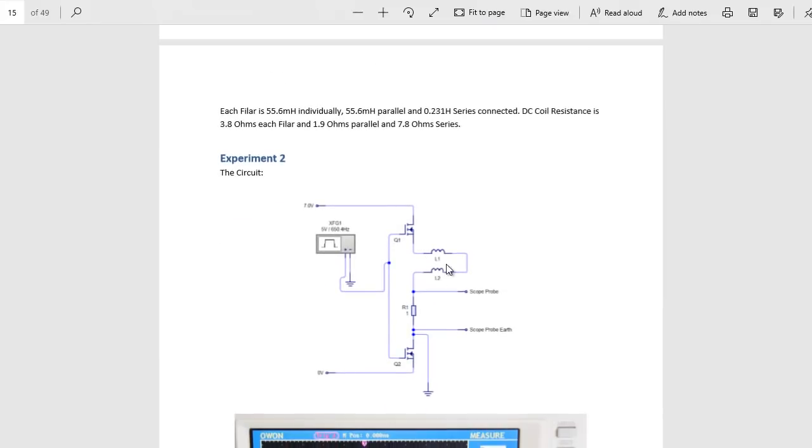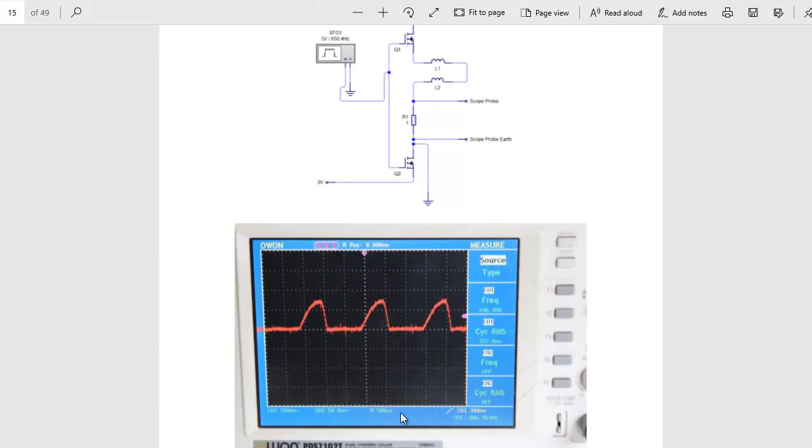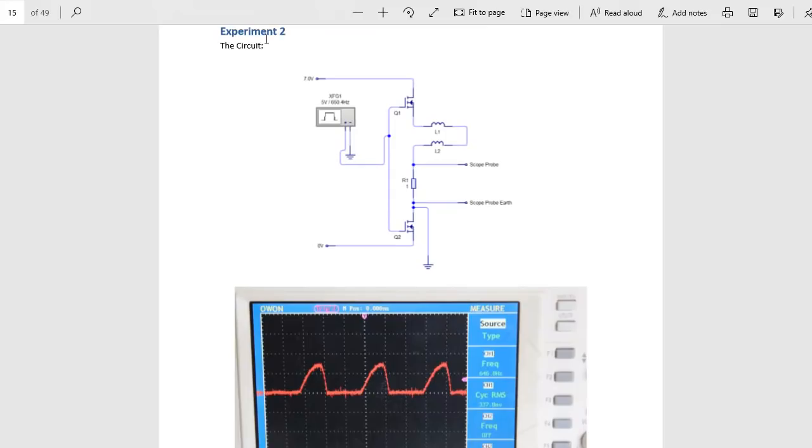If we make the coil non-inductive, and move to an even smaller time base, we have a much, much faster change, faster by many orders of magnitude. The current going through the coil can ramp right up to a maximum value in about 500 microseconds. So you can see it's much faster.